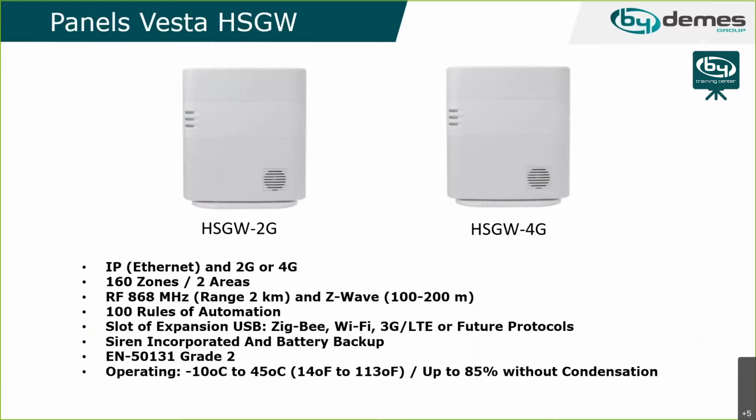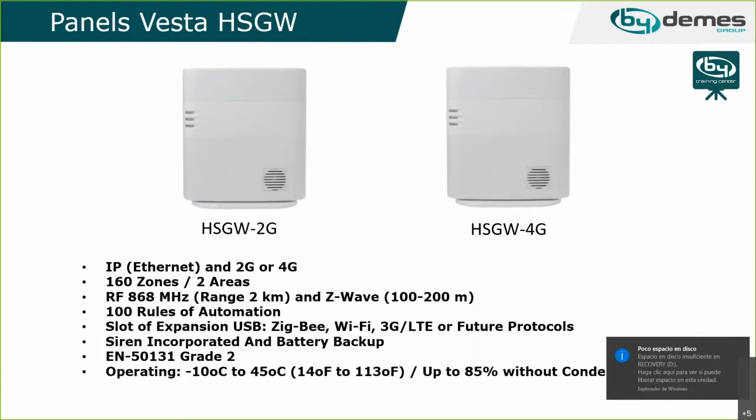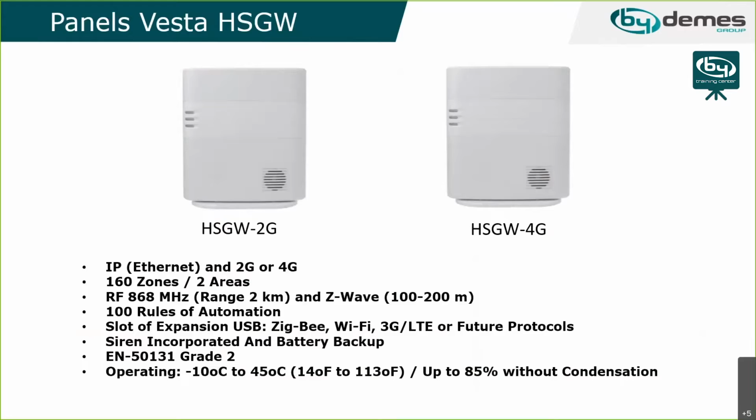We have two partitions, or two areas, in the panel. The panel is using radio frequency to communicate with all the devices. In this case, it's working on 868 megahertz. The range is very powerful, around 2 kilometers in open field. And the panel also integrates the Z-Wave protocol, which we are going to talk about, and also ZigBee, in the next pages.